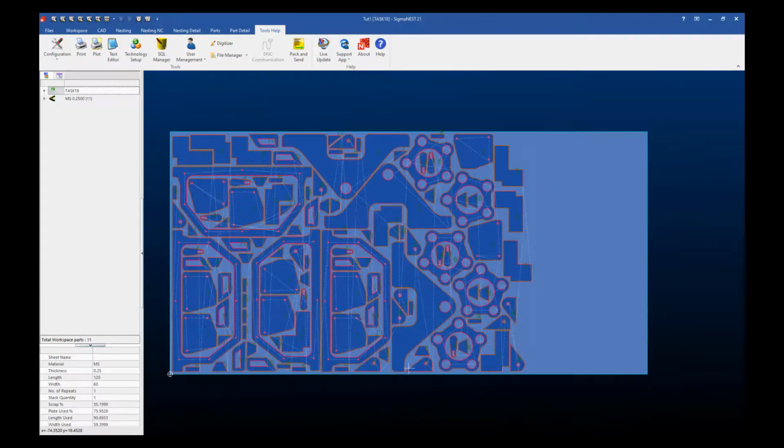It could be that the charts you pulled were outdated. It could also be that when your machine operator actually runs the program on the machine, they're dialing up the speed to make it cut faster. This is also something that's very common. So make sure that you have a good relationship with your operator on how they're actually cutting it. We do have some operators that will just hit go and take whatever feed rates are in the machine, and some of them know better and are comfortable with adjusting that feed rate. They might not do it on all parts, but they might do it on a couple.